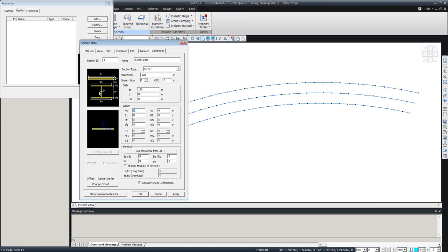So in this box, I'm defining the steel girder. Following this diagram, you can simply enter the dimensions. The total H of the web is going to be 72. The B1 will be 18 inches. TF1 will be 2.4. T-web will be 1.8, 18, and 2.4. Okay. So far you see the section is showing up here. So this is the section I'm going to use.